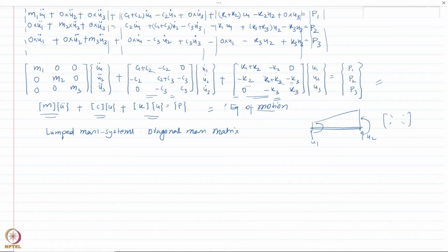Although, we will discuss later that we do not actually get our damping matrix like this, because in reality there is no damper between different stories, except where you actually install dampers. To get the damping matrix, we utilize other methods, using the mass and stiffness matrices, but that is for later discussion. What is important to note here is that if I have a multi-story building and I have defined dampers between different stories, then the form of the damping matrix would be similar to the stiffness matrix. All right, these are a few of the observations that I have made.